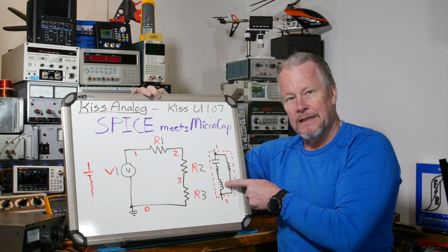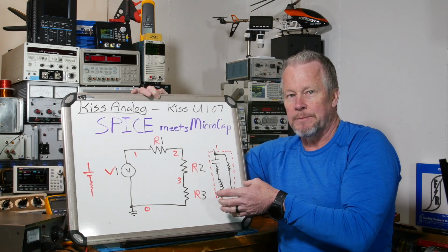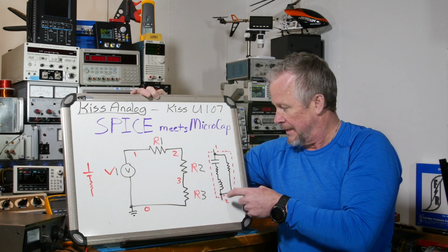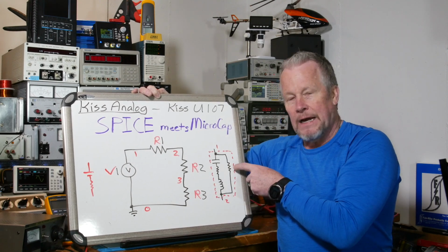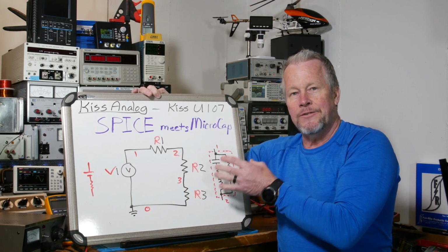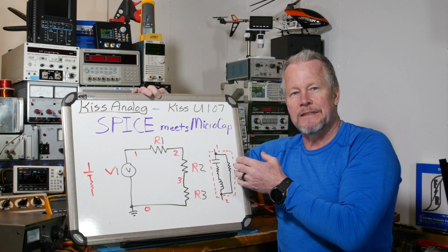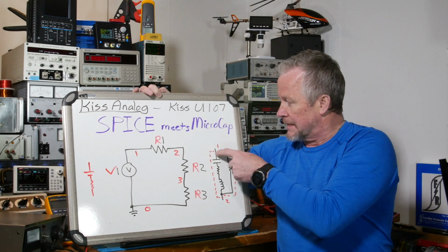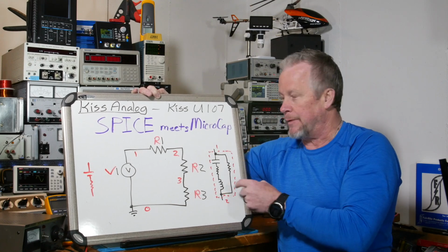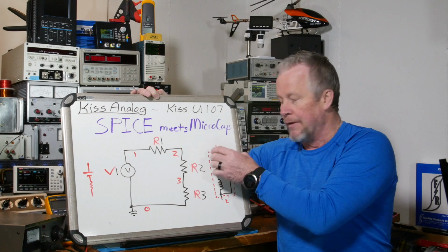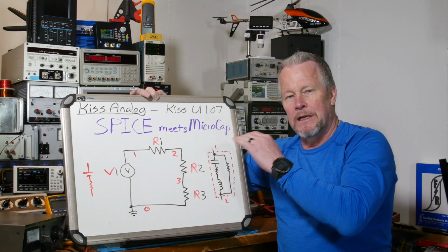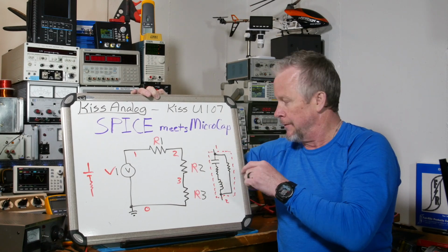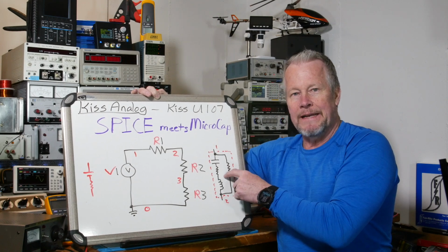You also have some inductance from the leads. Even surface mount, you're going to have some inductance. And then internal to the capacitor, you'll have some inductance, more or less depending on the type of capacitor, right? And then you have this leakage resistor that wraps around. When we talked about levels of models in the last video, this is going into that deeper level.